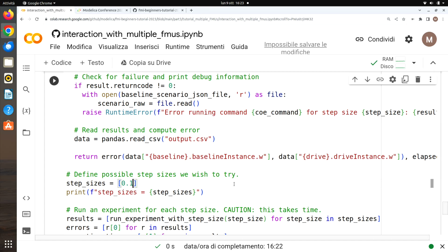If you have questions about this part, yes. Regarding your co-simulation, are you running your co-simulations at the same time, in parallel? No, in this case, I was running first one co-simulation, then another one, then another one, then another one, from the command line. In the application, there is an option to run many co-simulations with different parameters at the same time on multiple threads. It's also possible.